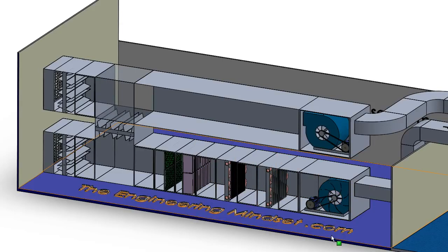And then we've got the supply fan here, which is pushing that conditioned air off and into the ductwork to go around and feed the floors, where it's brought back through this ductwork here, being sucked by this fan again, driven by this induction motor, and that's pushing that air into here. And then when it gets to here, the controls of the BMS system is going to decide how much of that air being drawn out will be sent back outside, and how much will be sent back into the building. And there is a reason for that.